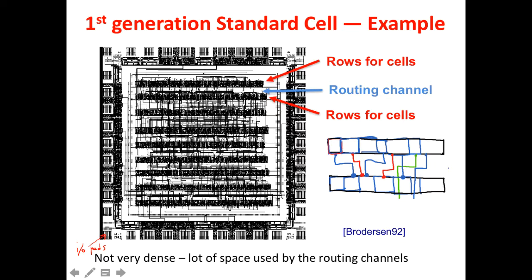This is the die. This is the piece of silicon in which you have the circuit. These are the pads for the input and output wires. And this is the area in which you have the silicon chip. Actually, in the case of standard cells, the typical situation was that you have rows in which you can put the cells. And the cells were designed in order to have all the same height and different width depending on the complexity.